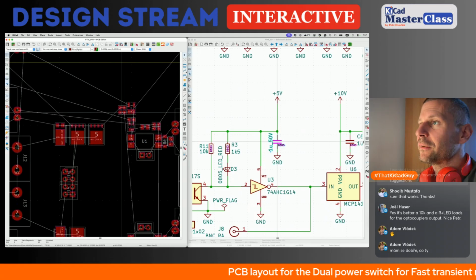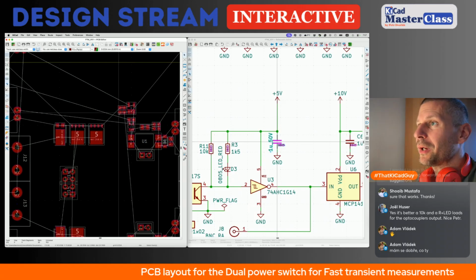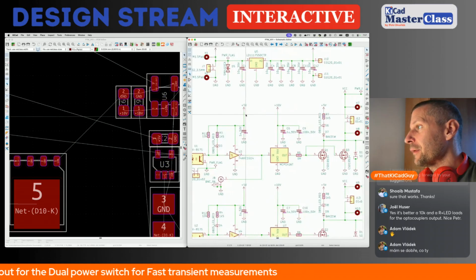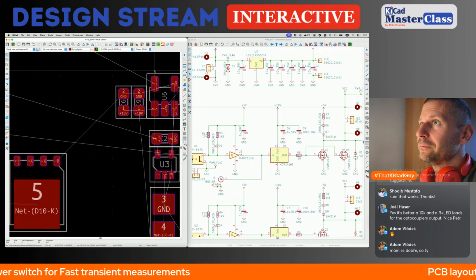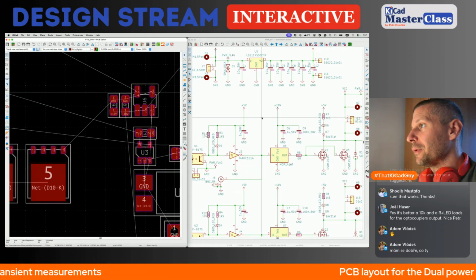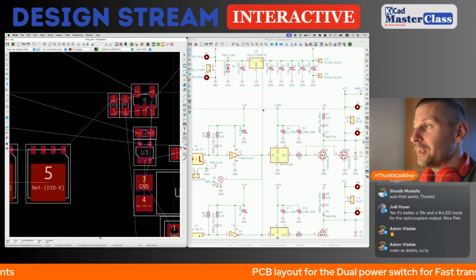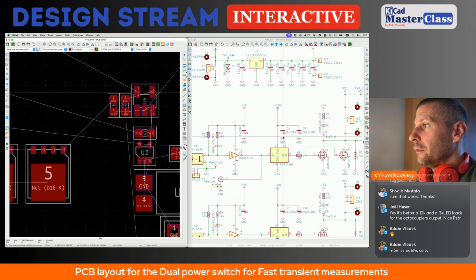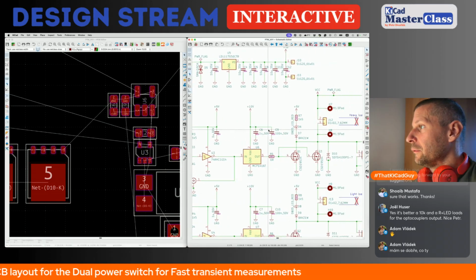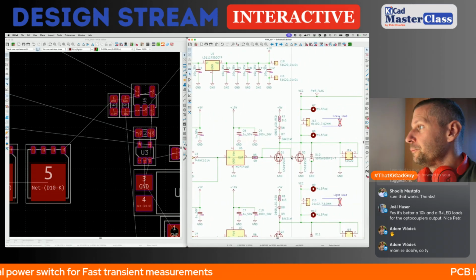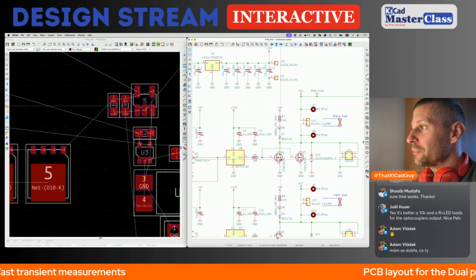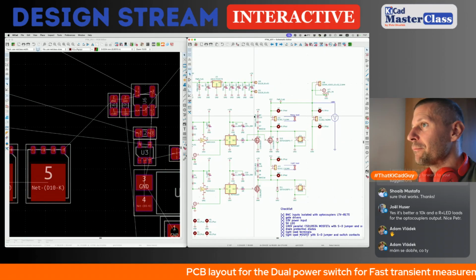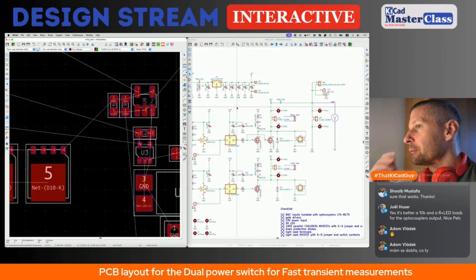There will be a mix of 2 voltage domains, 10 volt and 5 volt. Nothing pleasant, but not a big deal. I have the 10 volts, at least 10 volts for switching the MOSFETs to reach their lowest resistance.